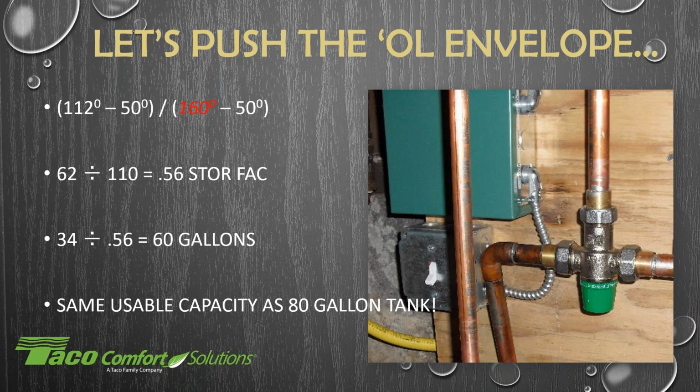So when we're talking today about our mixing valves, we are talking tank style, where you have that stored temperature. When you look at tankless, you size your tankless based upon the need of the house, because it has very little stored hot water in it. They do have their own temperature settings. You're not going to get a tankless to give you more.